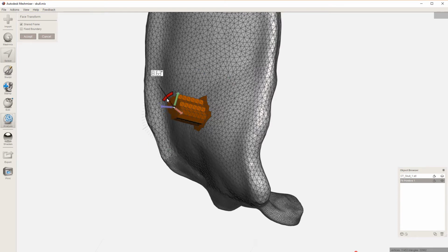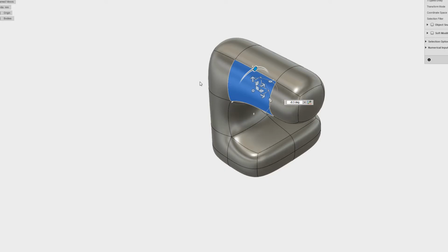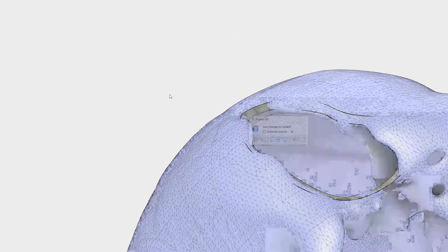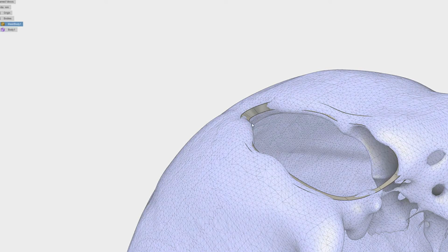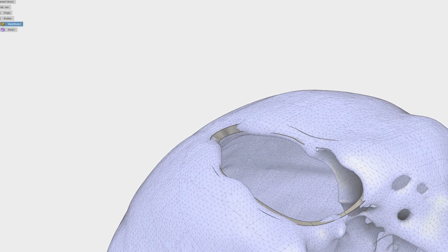It's easier to figure out mathematical computations for quads than for tries. So what I'm showing here is that you can use the tries as a template to create quads, and then everything inside of solid models is quads or more. You could have 5-sided, 6-sided, but you start to get into some weird things with more than 4 sides. You want to try to keep it on 4.